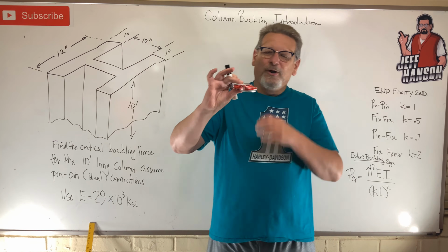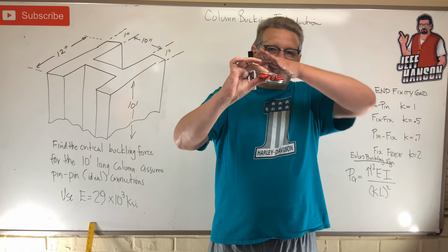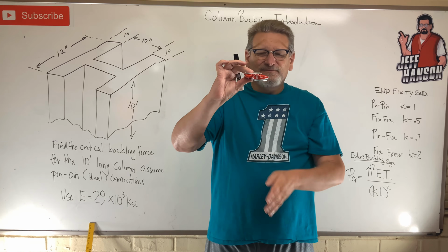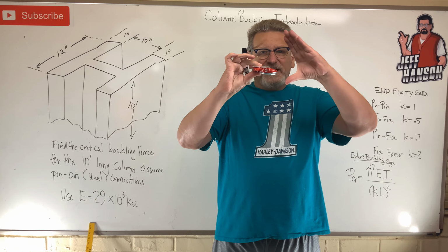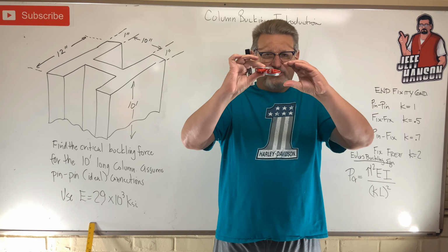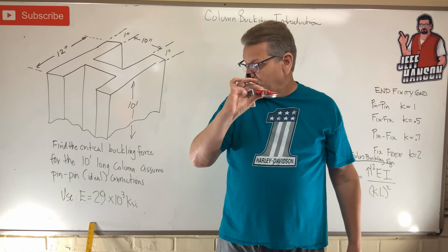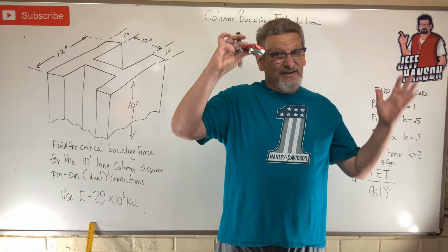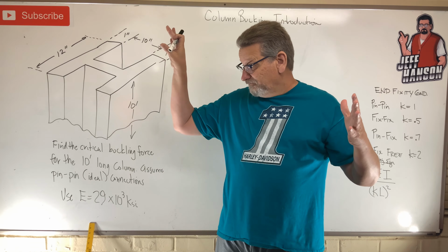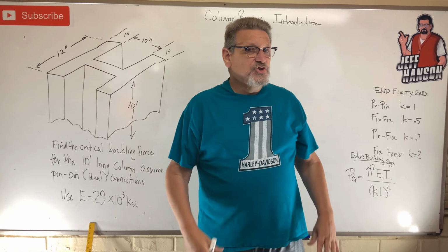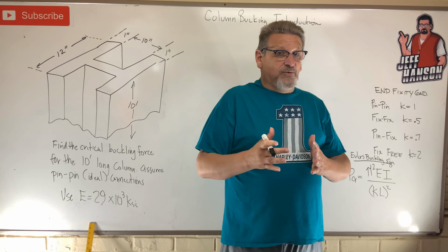Now look how short columns fail. They don't bow, they don't buckle. They crush. They collapse upon themselves. That's a short column failure. That's totally different than a long column failure. Now we know that. So, like I said, we're going to be dealing with long columns.